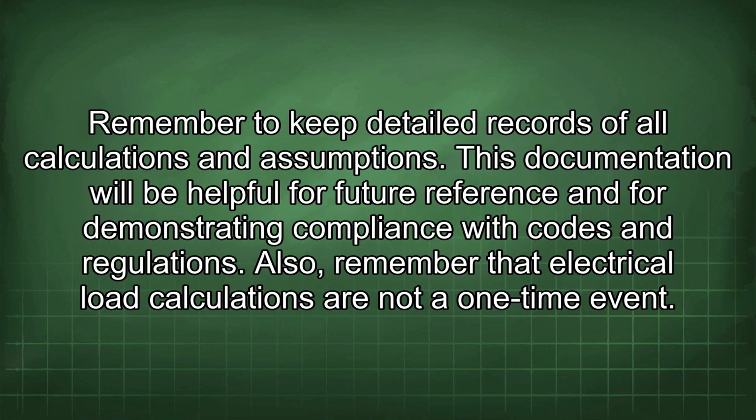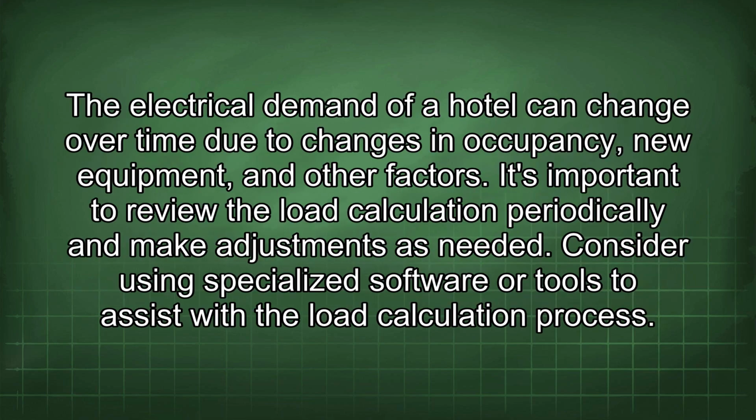Remember to keep detailed records of all calculations and assumptions. This documentation will be helpful for future reference and for demonstrating compliance with codes and regulations. Also, remember that electrical load calculations are not a one-time event. The electrical demand of a hotel can change over time due to changes in occupancy, new equipment, and other factors. It's important to review the load calculation periodically and make adjustments as needed.